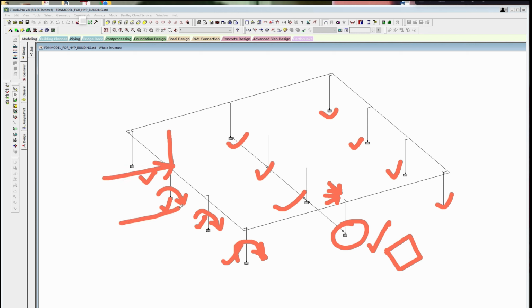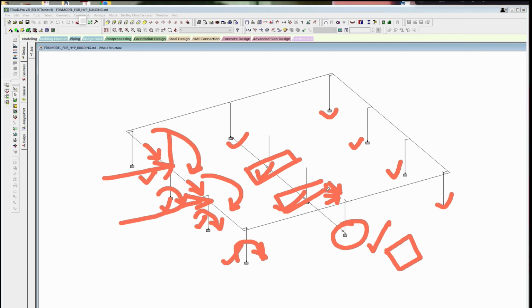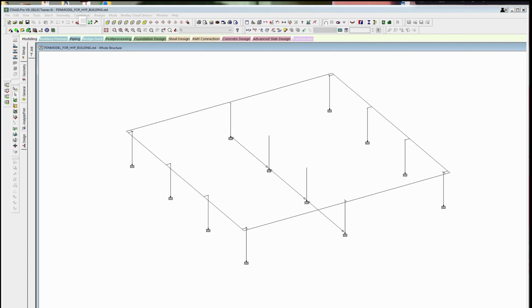There will be horizontal force in this direction also, but about these directions the columns on the superstructure are not fixed, they are released. So along these directions much of the moment will not be created. So we will have rectangular footings for columns which are fixed in one direction. Let us now take the reactions.